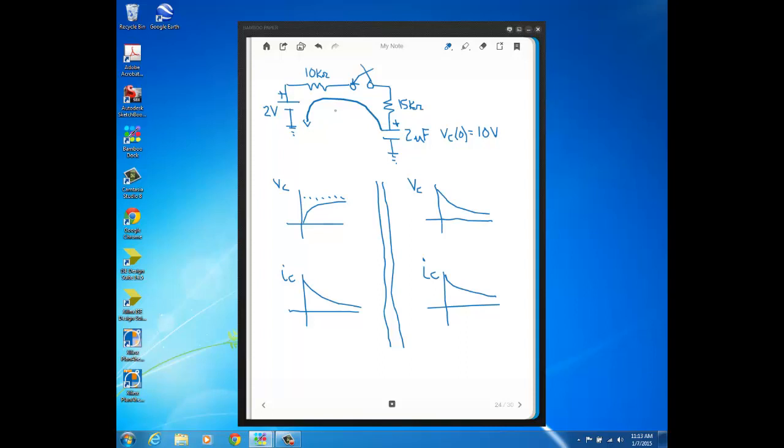Because as we know, current's going to flow from the higher electric potential, the higher voltage, to the lower electric potential, the lower voltage. So this is a discharging case because anytime current leaves the higher voltage end of a capacitor, and here is the higher voltage end indicated with the plus polarity symbol, well, this means that the capacitor is giving up energy to the circuit, okay? That it's supplying power since the current is flowing out of the higher voltage end.